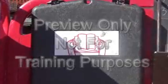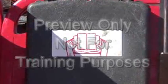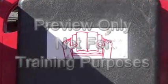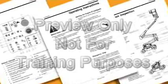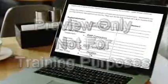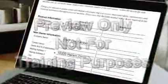Operation manuals provided by the manufacturer must be stored in a weatherproof compartment on the MEWP. Employers must ensure operators read and understand the manual or have it explained to them. MEWPs must be registered with the manufacturer to ensure any safety-related bulletins are received.